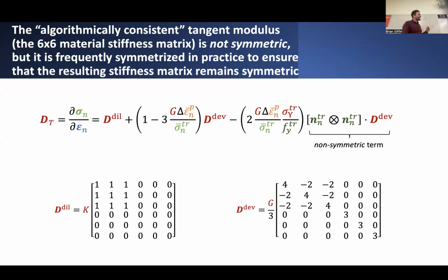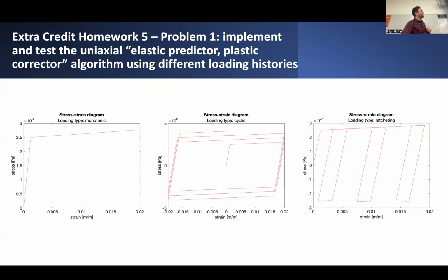But the whole point of this is, once you introduce these algorithms for updating the plastic strain in this fashion, it introduces some of these other complications. So just be aware that whenever you're dealing with multi-axial plasticity models, this elastic predictor plastic corrector step is nonetheless an approximation as to how we should go about updating the plastic strain. It's not really an exact procedure for how you should do it. It's an approximate way of updating things that is nonetheless rather convenient and intuitive. Okay, so that's as much as I wanted to discuss on this subject of algorithms for plasticity.